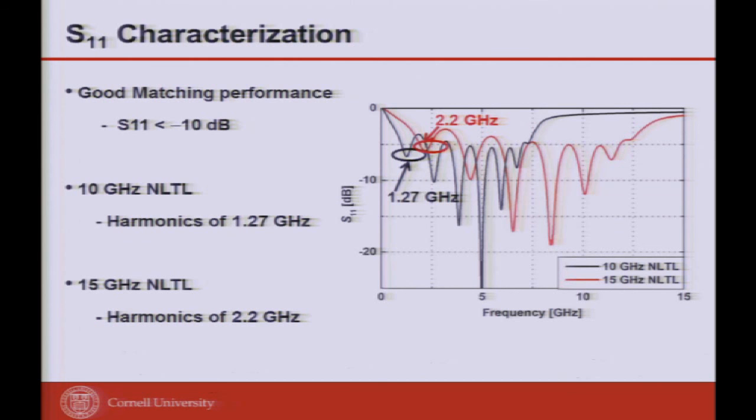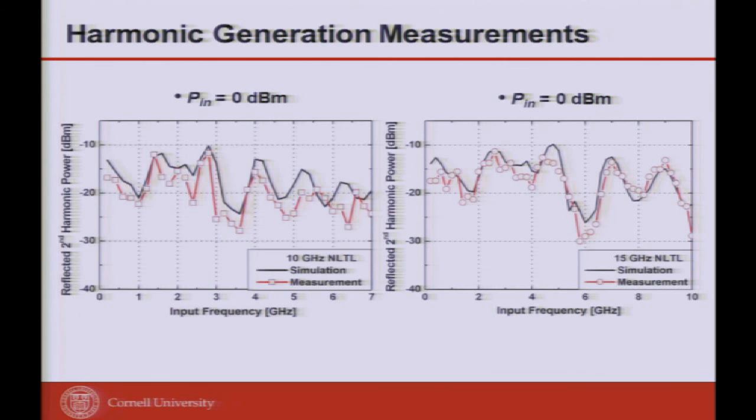We characterize the nonlinear conversions. These oscillatory signals come from the oscillatory impedance match. When the harmonic generation does not match the impedance, the S11 will have a peak, so it relates directly to the impedance. Harmonic generation in the reflective design is about minus 10 dB, a minus 10 dB loss for the harmonic generation, much better than the discrete one already.